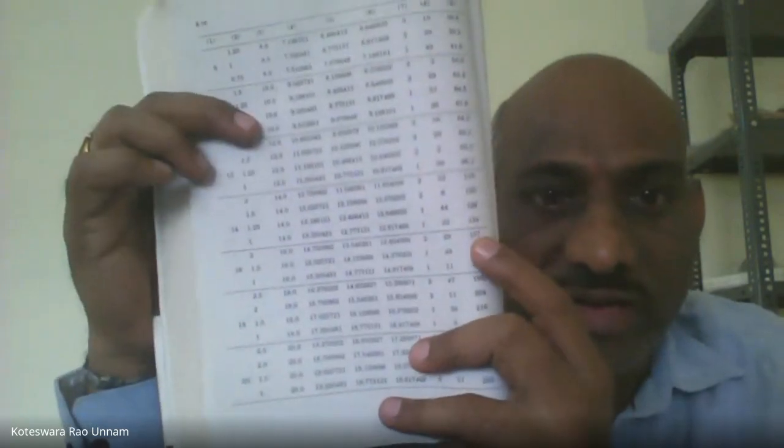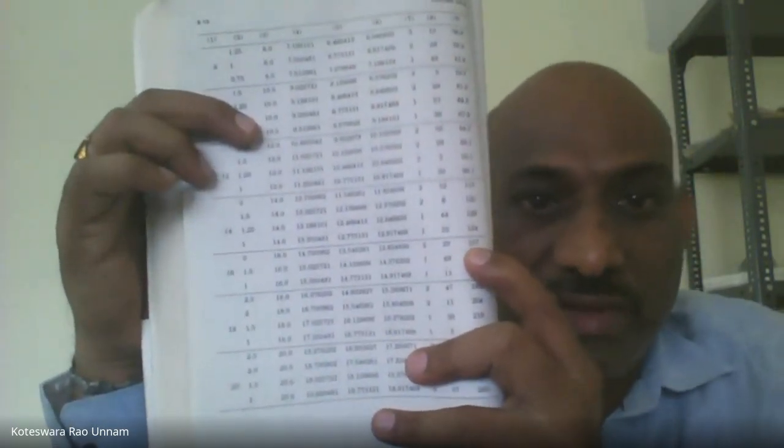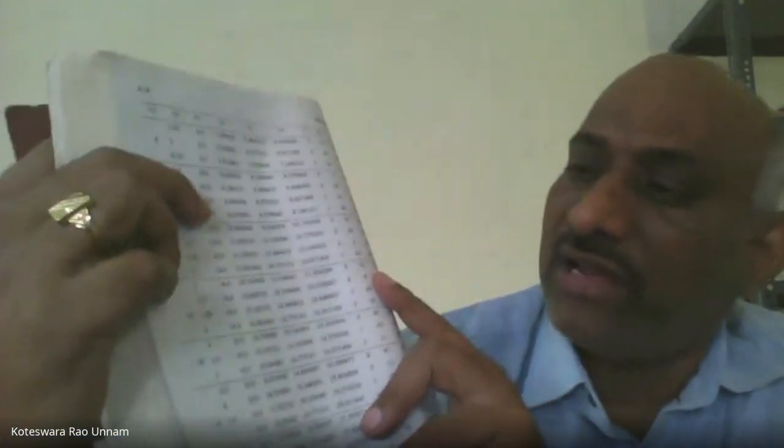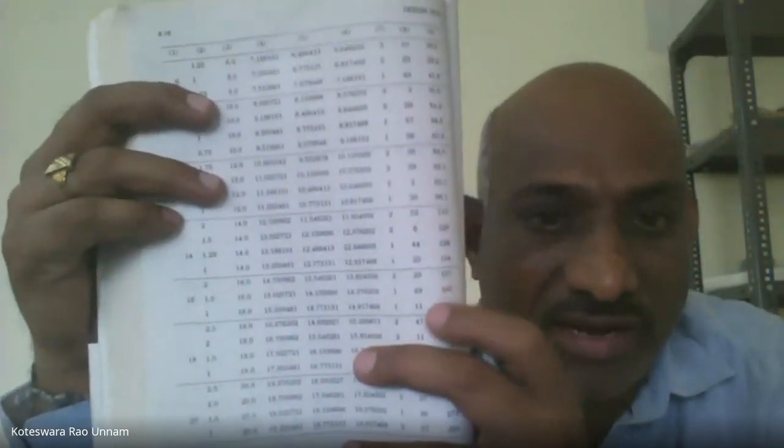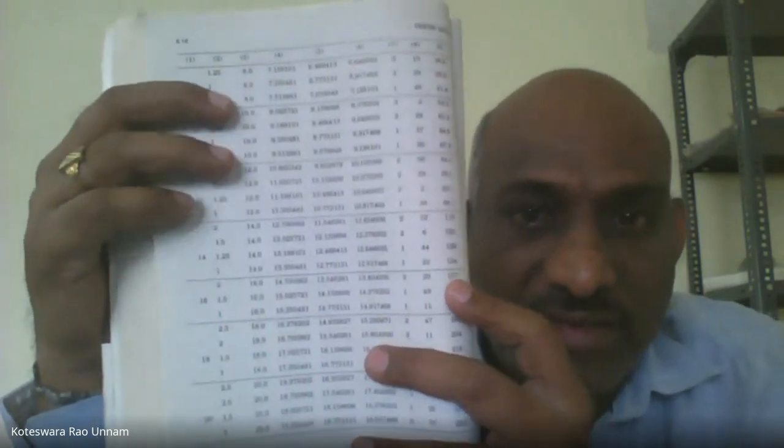If I go to M16, you can see it here. I'll open it like this. So I need to keep it here only. For M16, you can see the values here. So this is M16 for coarse series. The first value you need to take here is going to be 157. Now if I go for M14, the value is only 115. I cannot select 115, so I have to select this one, that is M16.